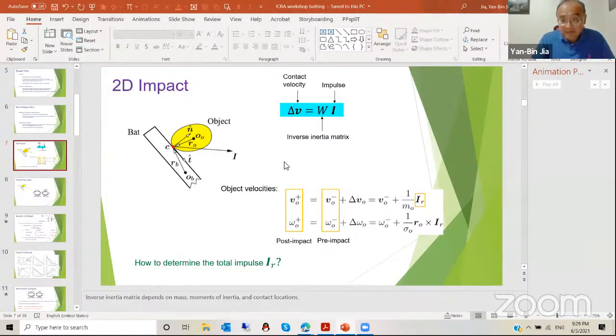I think there has been some work, like by Khatib's group, modeling the robotic arm inertias during impact, but they are using Newton's kinematic restitution law for the modeling. So maybe we could use that and try to see how to fit it into this energetic restitution model. Okay, thank you very much for the answer.